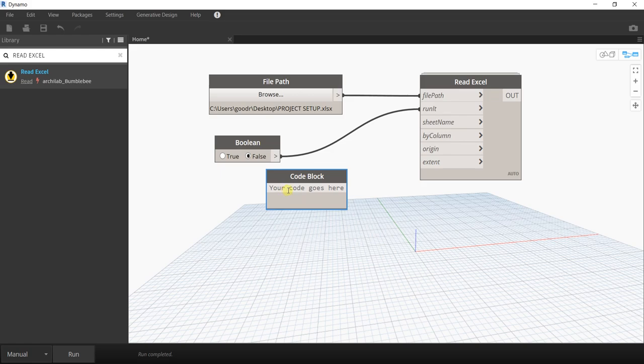So what is the value that you would like to be inserted here? Just like what I have said earlier, make sure the spelling that you're going to type here is the same as the one in your Excel. So if that is levels, make sure you put levels here. But if you're going to type here a value or a text, make sure you put quotation marks, open and close.